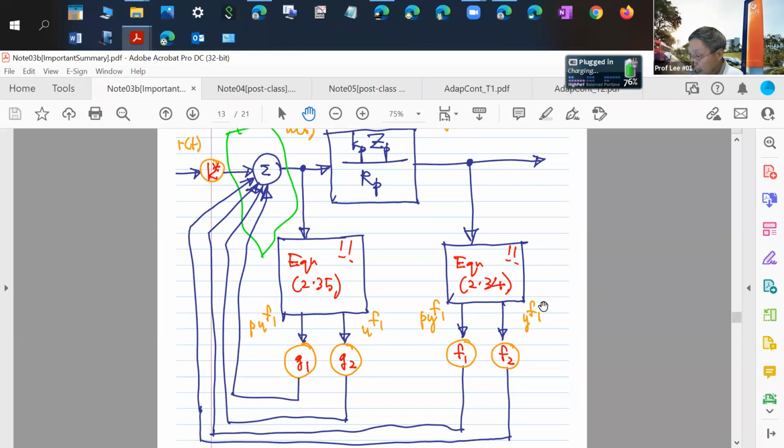But if you take n of these signals and another n of these signals and you put them together in a vector, these 2n signals, proposition 1 says, exactly form a state vector of your original system to begin with. Okay, then you also have to be very clear, right? This is an n order system. Now you take these 2n signals, put them together in a vector, they form the state vector of this system.